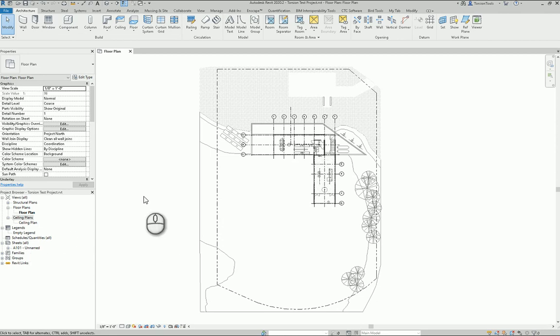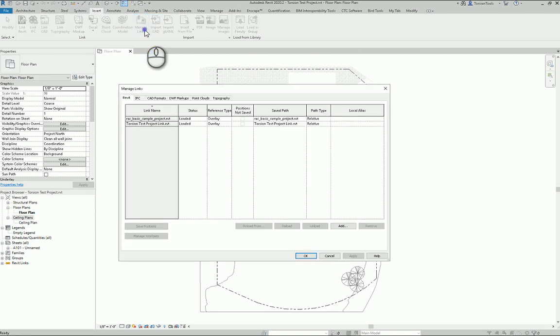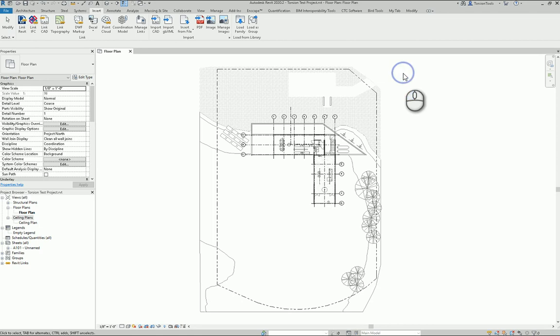The way legends copy between projects, you have to have at least a singular legend that exists already in the project. Most projects that have kind of legitimate things going on in them should already have a legend. This one doesn't because it's a really lean test project, so we just have that empty legend there. So what we want to show here is we have a couple of models linked in, the Revit Architecture Basic Sample Project, and then another test project linked. It just has some pretty simple information that we can use to kind of show how this process works.